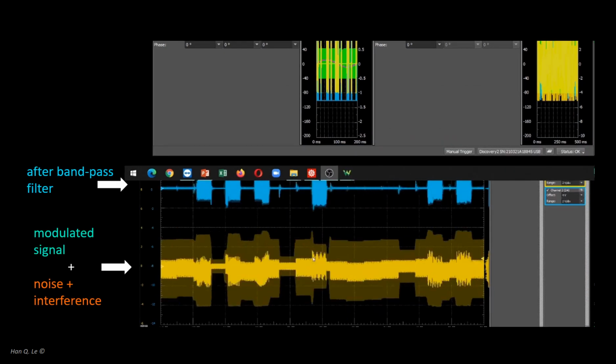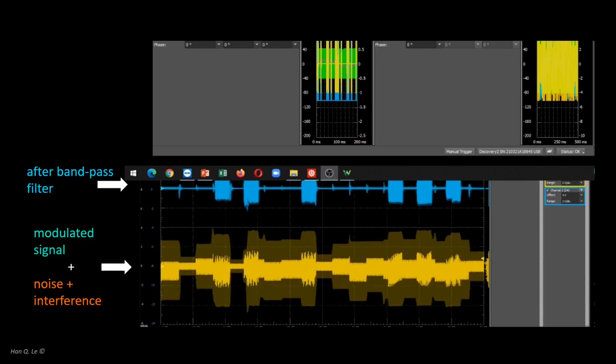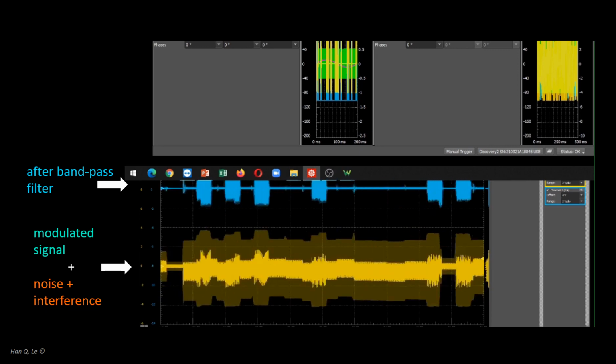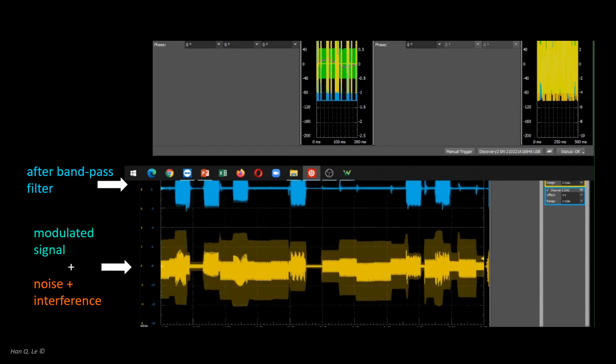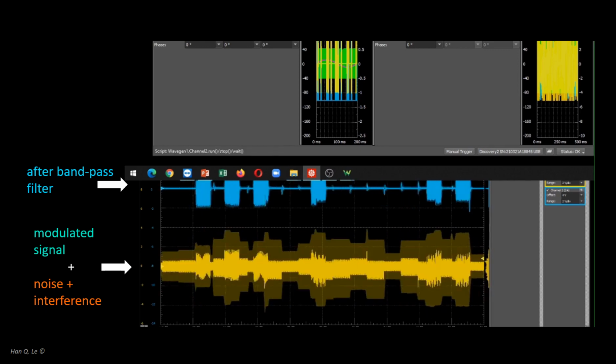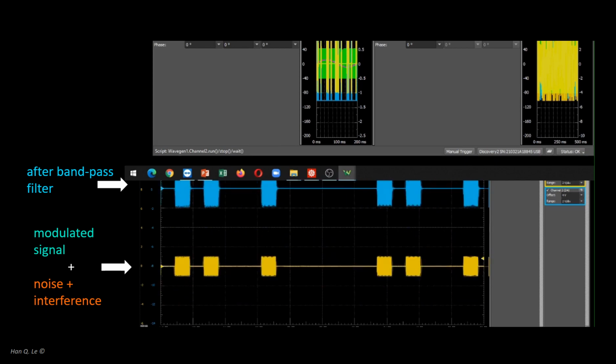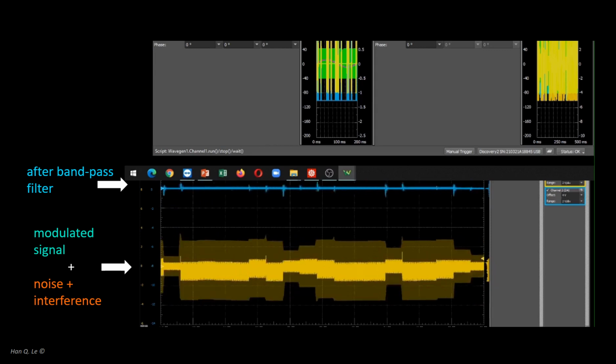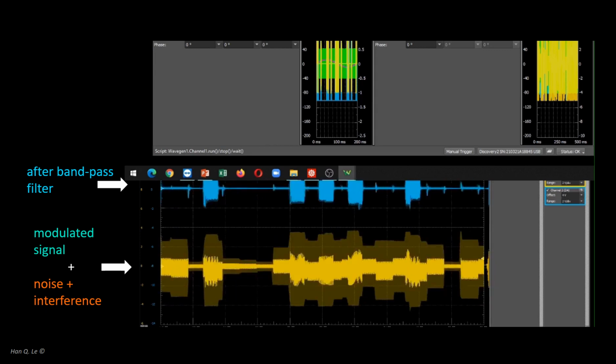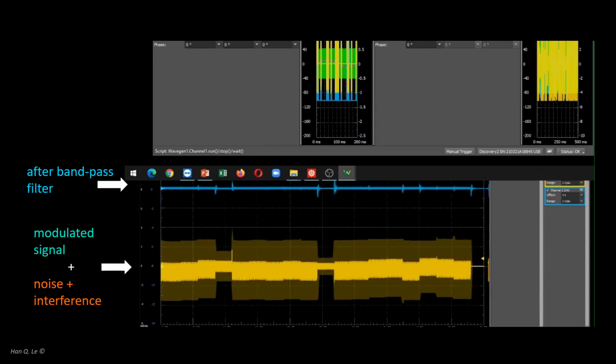To identify the signal sources, the following shows the bandpass output for signal alone, or for noise and interference alone, or for both signal and noise and interference. Noise and interference is turned off. Output shows only the desired data signal as expected. There is a little resonance amplification, which is the property of this particular filter design. Signal is turned off and on. Only spikes remain as noise and interference are largely attenuated. The bandpass filter performs as expected.